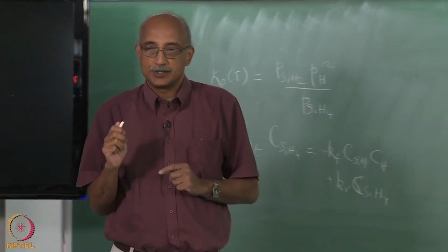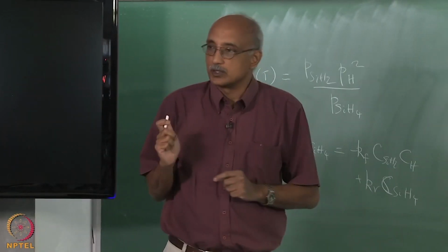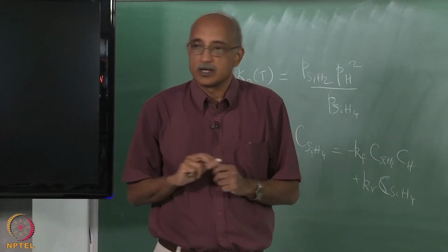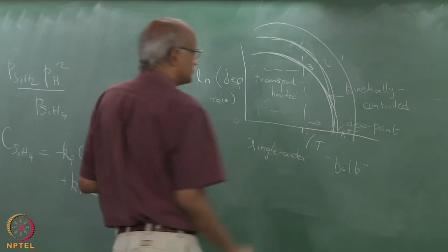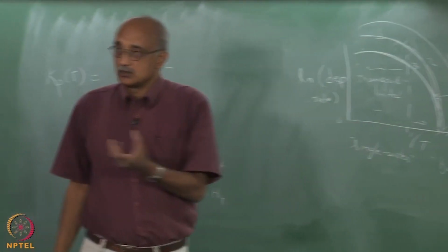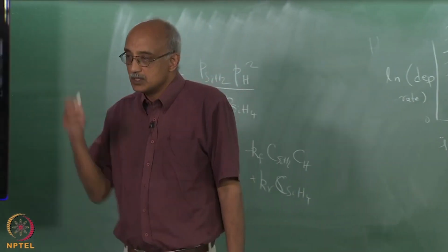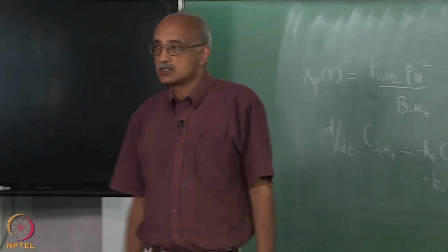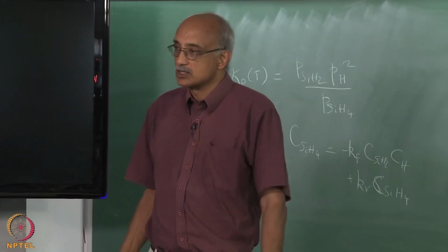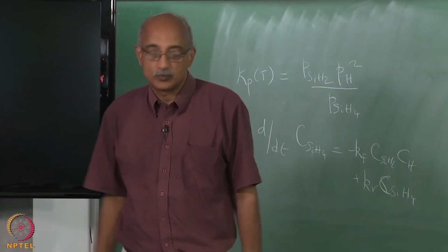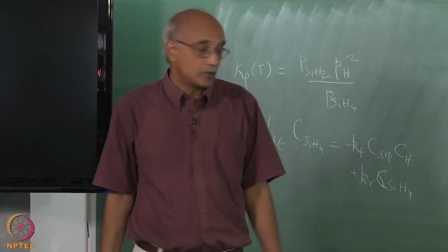When you double the concentration of the reactants, you do not change the dew point, right. So, eventually it will converge like this, because the concentration only makes a difference in the transport limited regime. Once you get to the thermodynamically constrained regime, it has less of an influence. So, eventually the two curves will converge and you will essentially come to the same dew point. Anyway, as I said, a lot of interesting things to think about.